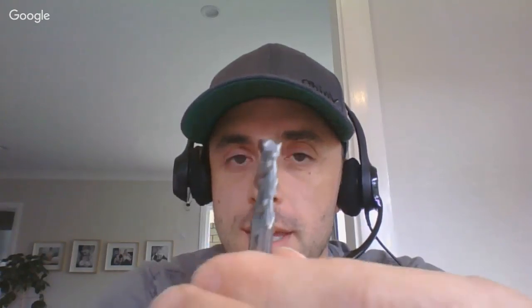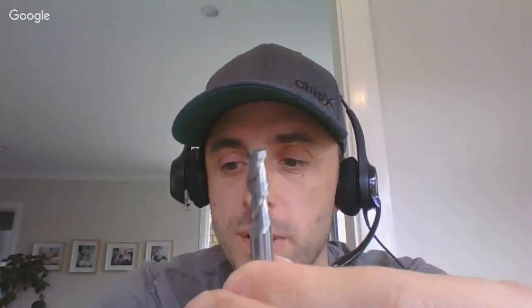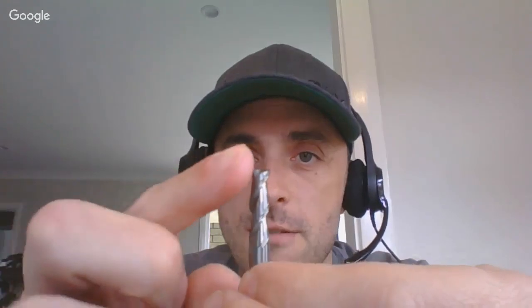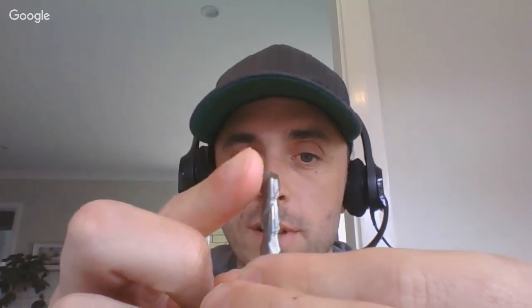But really, the way you can break it down is by rotating a round tool in material. The spindle RPM, or how fast that spindle is turning, is going to dictate how fast that cutting edge is actually traveling through the material. So even if that tool is not feeding, or it's not moving in a straight line, just having it rotating will be rubbing the surface of the material.